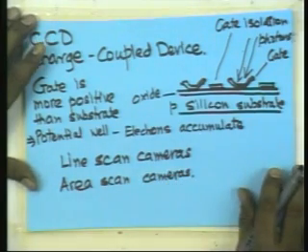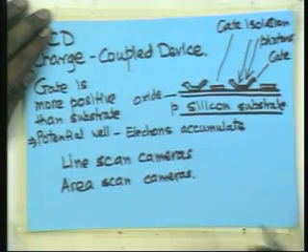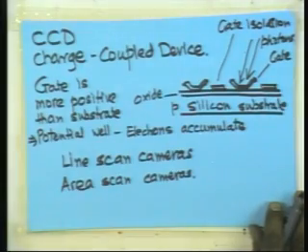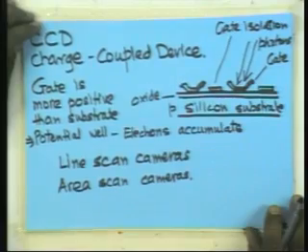Okay, line scan cameras are very common in, let us say, Xerox machines, where you look at one line at a time and then scan through by moving the carriage, which basically scans the whole page. It is used for inspection type of systems or photocopying type of systems. Area scan is used for video images, and area scan basically replicates the line scan technology in the other direction also. So, the basic structure is something like this.